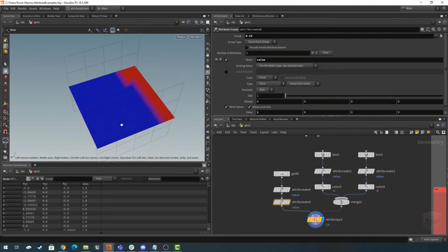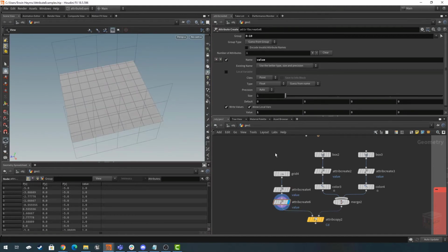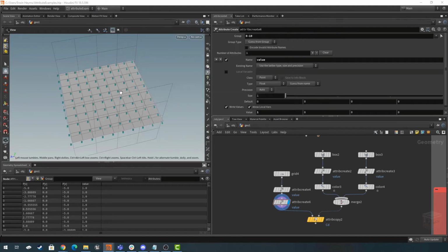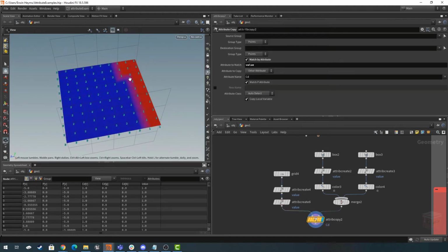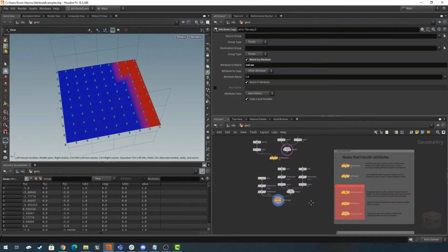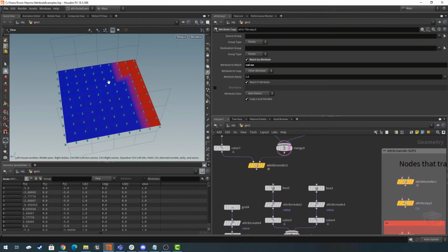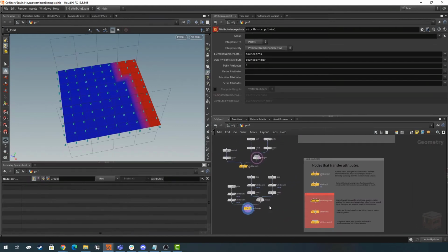And now you can see that it's actually copying from both based on this attribute. So let's go ahead and visualize this. Let's grab this value here, and I'm visualizing it as markers. So we can see how values 1 are marked red and values 2 are marked blue. That's pretty useful. It's also a bit more efficient than, say, the attribute transfer, because it just transfers between 2 point sets, and also it can actually be compiled, but we won't go into compiling right now.